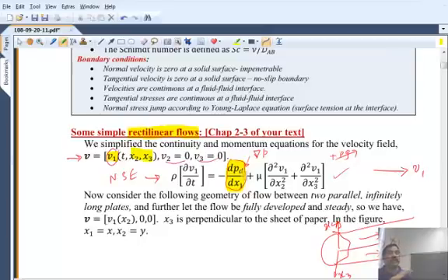So I could have a moving boundary and the fluid sticks to that, so that can generate a flow inside any domain. For example, a piston in a pump or a centrifugal pump, the vanes, the turbines, these are all moving boundaries that cause the fluid to move. So these are the two typical sources of external excitation that can cause the flow to be non-zero. If dp dx is 0 in this case, then the flow has to be 0. There is no flow. Everywhere the velocity is 0. So you get a trivial equation once again. Does that answer your question?